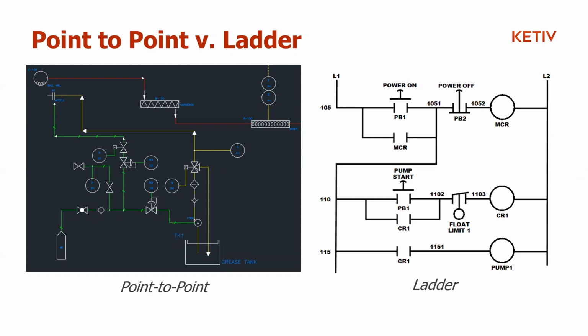On the right is the, I don't want to say more traditional ladder diagram, but that is a ladder diagram. Called so because it looks very much like a ladder with these big vertical buses along either side. And then you see these individual rungs that have these self-contained circuits that represent various things. Here on this particular ladder diagram, you see this motor control relay and a few buttons that connect all together, and that represents a single step of the ladder, right? And that's great, that's fine.